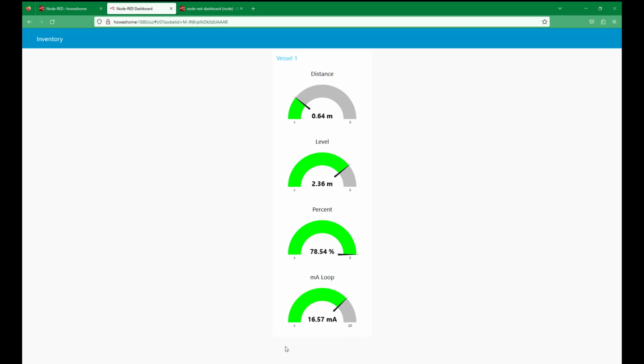It'll be very difficult for me to cause a fault on this, so what I'm going to do is remove my wire rather than trying to fault the instrument. So let's do that now. I've gone to 0 milliamps. My distance, don't forget it's the other way around. So now I can do some clever things in the background with this. Rather than just letting it go to 0, I can start programming thresholds that will generate alarms that will appear on the screen, but also I can get it so it will generate an email and send an email message to somebody that the level sensor's failed.